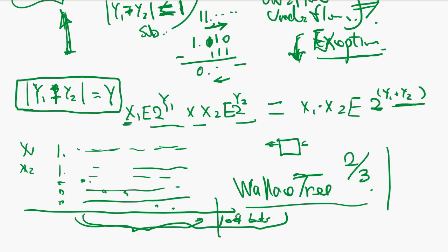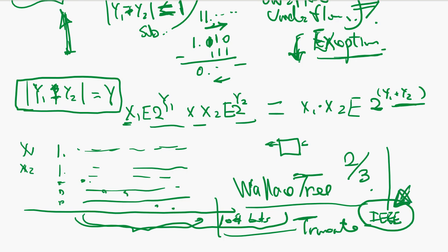Now again, we use truncate, and you worry about, well, IEEE said we should provide round to nearest, but it's going to be a lot of hardware to be added, and cycle time for the calculation, and sometimes it's not worth it. So it's a matter of conforming to the standard, and also an accuracy issue.